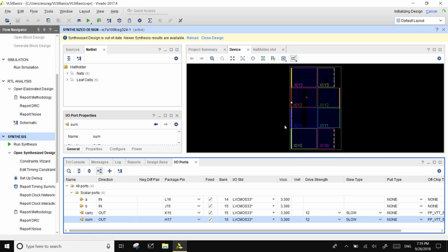There are no gates in FPGA. Only lookup tables, flip-flops, and multiplexers. Well, there may be gates inside them, but it is not visible to you how they are implemented.